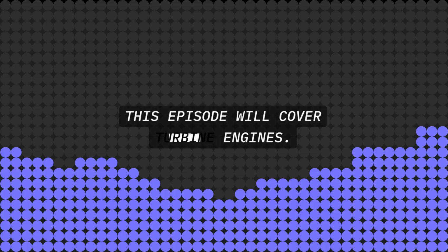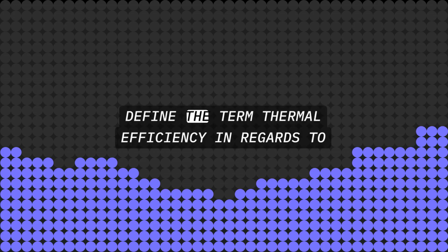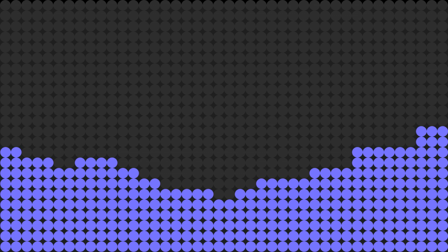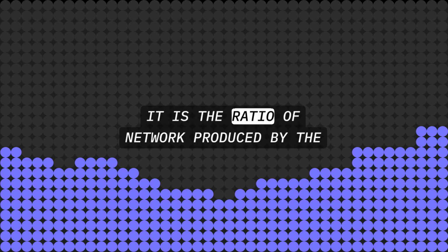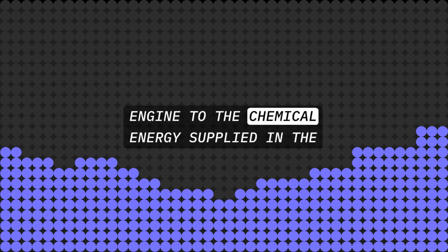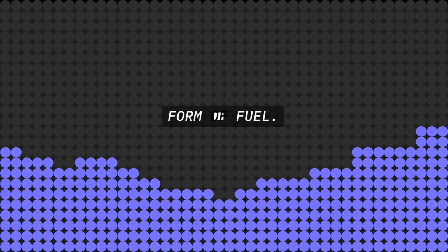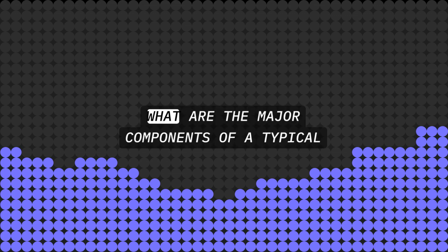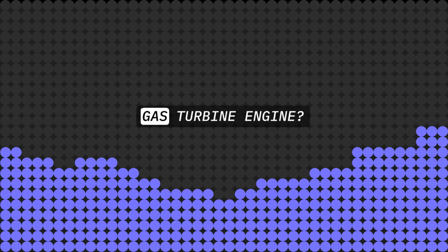This episode will cover turbine engines. Define the term thermal efficiency in regards to aircraft engines. It is the ratio of net work produced by the engine to the chemical energy supplied in the form of fuel. What are the major components of a typical gas turbine engine?